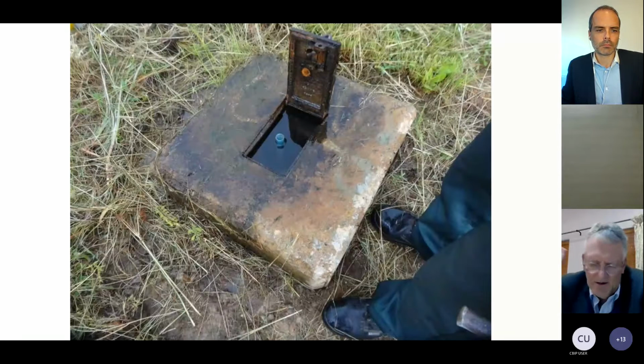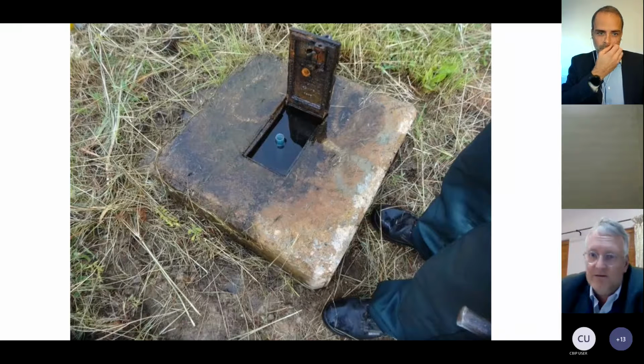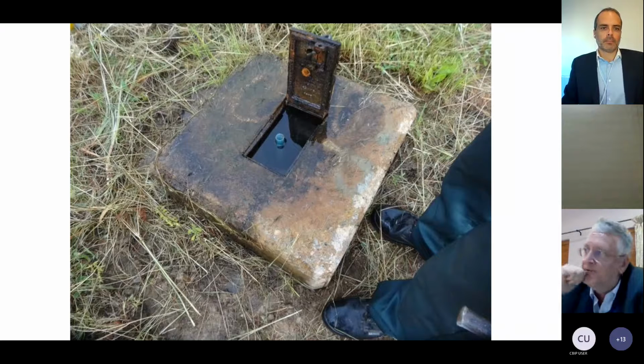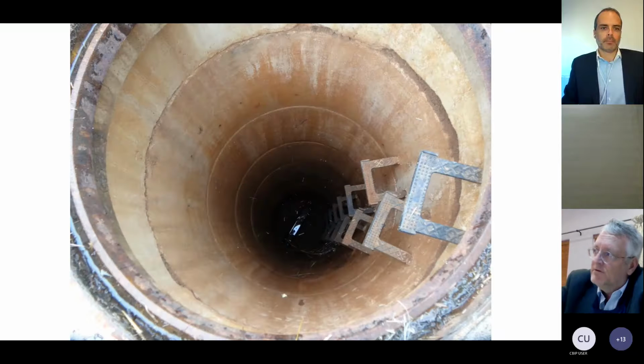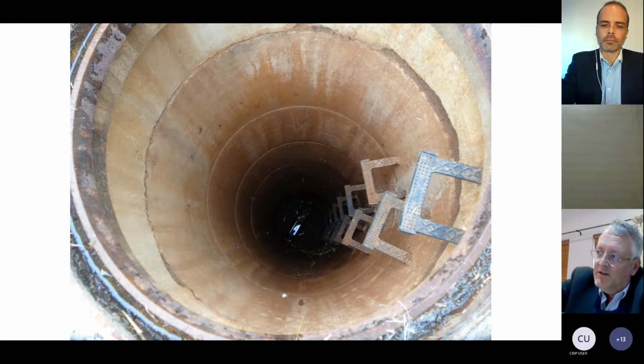And we've highlighted the importance of inspection. If you go to site, the standpipe piezometers downstream of the toe in this section, you actually see that there's a lot of flow that comes from the standpipe piezometers. Within 3 meters of this particular standpipe piezometer is a pressure relief well that is 3 meters deep.